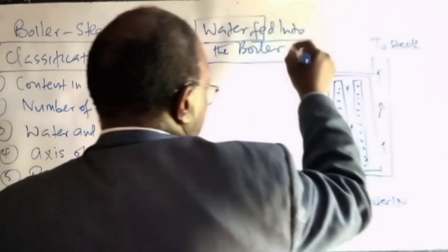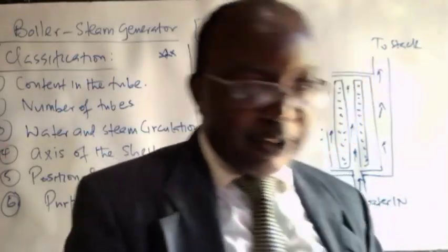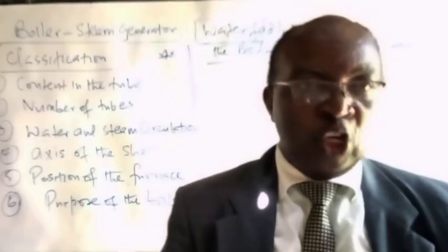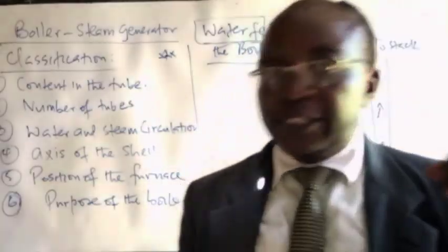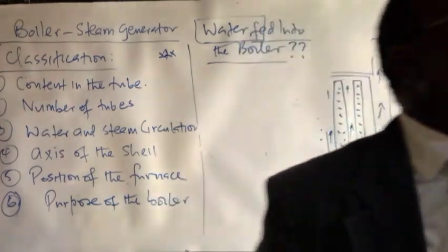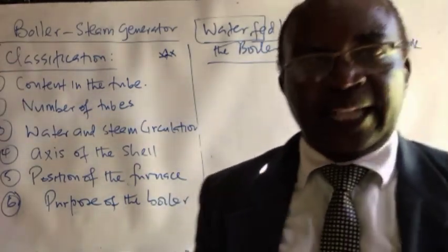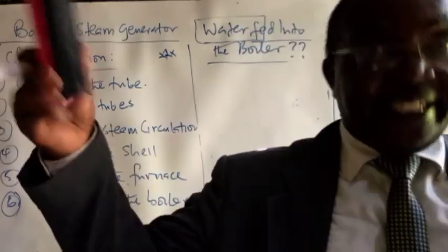The water you feed into the boiler makes a lot of difference, because if that water has a lot of dissolved solids, then that is not good for you, because there will be scaling on the walls. What is scaling? There will be depositions on the wall, and what can that do? That can make the system become adiabatic, in quotes.